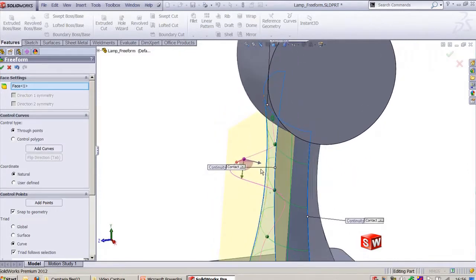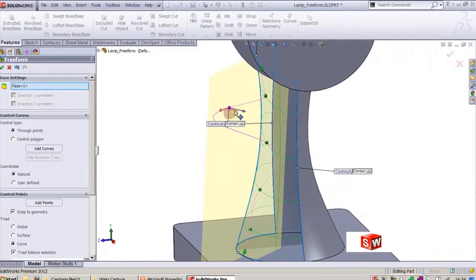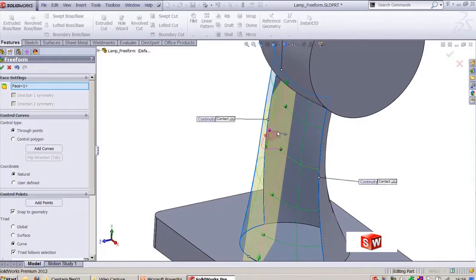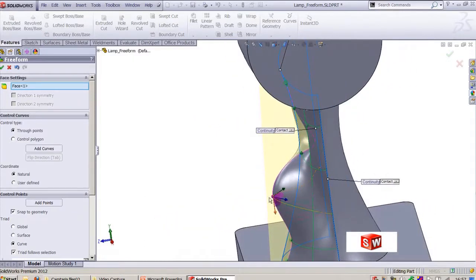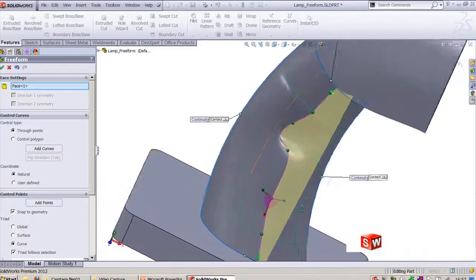And you can see here we are just about to drag this. I don't want to drag this much. I will reduce this up to here, but we are doing it in a rough way. So what I will do here, I will just drag in this way, and this line has to be dragged in this way. So here you need to understand the face we are selecting here is modified using these dragging points, and these dragging points are created using freeform.